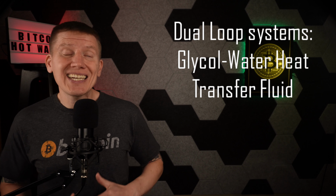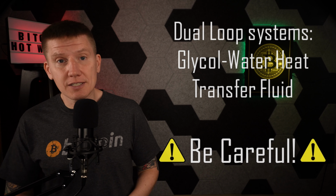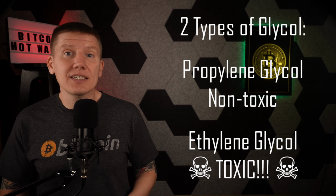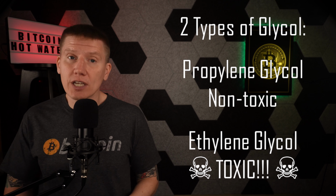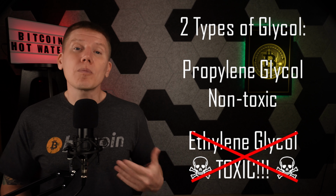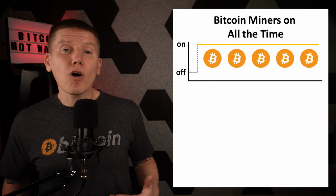In contrast, if you're using a dual loop system, it's really important to choose the right type of glycol in your system. Propylene glycol is non-toxic and won't make you sick. Ethylene glycol is toxic and can really cause you or your family harm if it leaks into your drinking water. So it's a really good idea not to use ethylene glycol if you're going to use your immersion system to heat your home water.